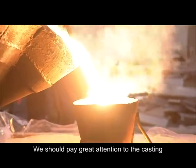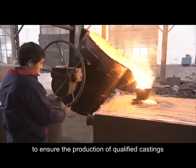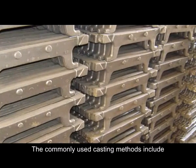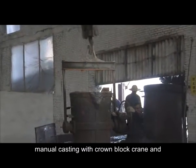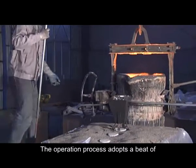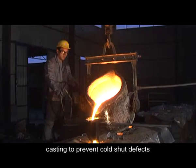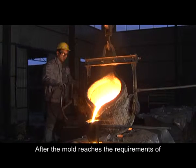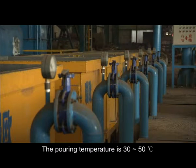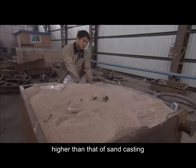We should pay great attention to the casting speed, temperature and vacuum system in order to ensure the production of qualified castings. The commonly used casting methods include manual casting with the crown block crane and automatic casting with the casting machine. The operation process adopts a bit of slow, fast, slow and maintains continuous casting to prevent cold shut defects. After the mold reaches the requirement of pressure maintaining, we should stop the pump. The pouring temperature is 30 to 50 Celsius degrees higher than that of sand casting.